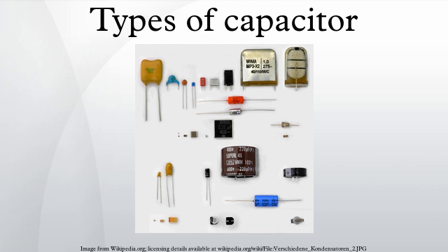The aging follows a logarithmic law. This defines the decrease of capacitance as a constant percentage for a time decade after the soldering recovery time at a defined temperature, for example, in the period from 1 to 10 hours at 20 degrees Celsius. As the law is logarithmic, the percentage loss of capacitance will double between 1 and 100 hours and triple between 1 and 1000 hours and so on.